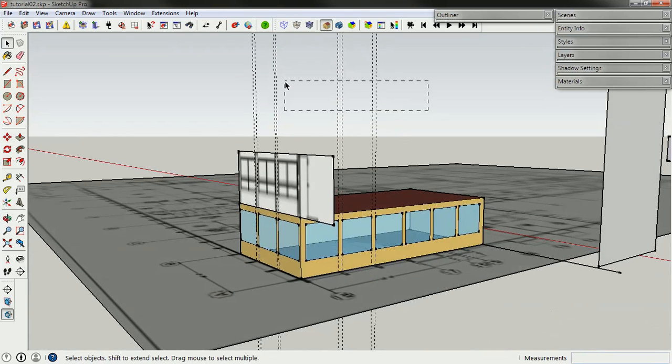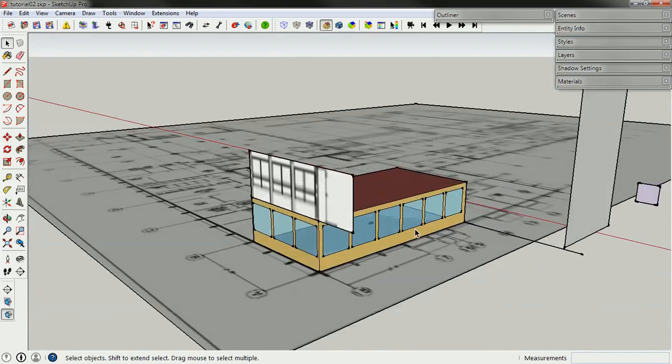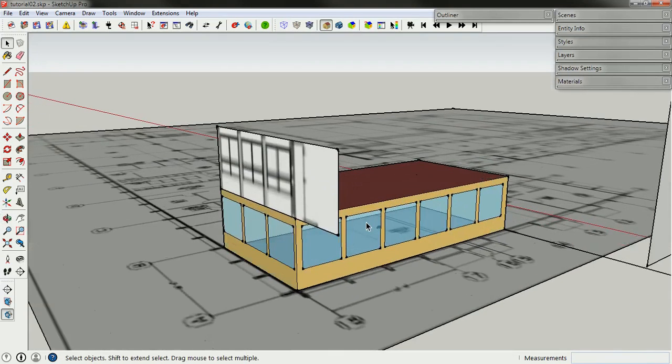Okay, so now I've got a thermal zone with windows in it, and that will cause heat gain and heat loss. This is a good time to save. In fact, I probably haven't been saving enough. It's really important that you save because OpenStudio has a really bad Control-Z functionality. It often will not let you go back, and I really encourage you to save as much as possible. And there's a good versioning technique I use that'll help you to do this.